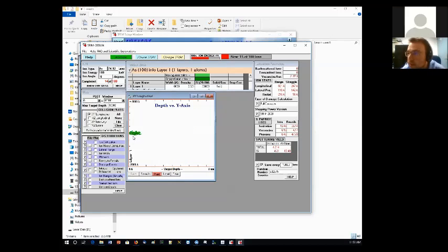But I want you to see one thing. It's not just showing us the arsenic, but it's showing us the damage that it's creating inside the crystal too. These green ones are now the interstitials. They're the knocked off silicon atoms from the crystal. Wherever the arsenic is going, of course, it's taking a little longer.